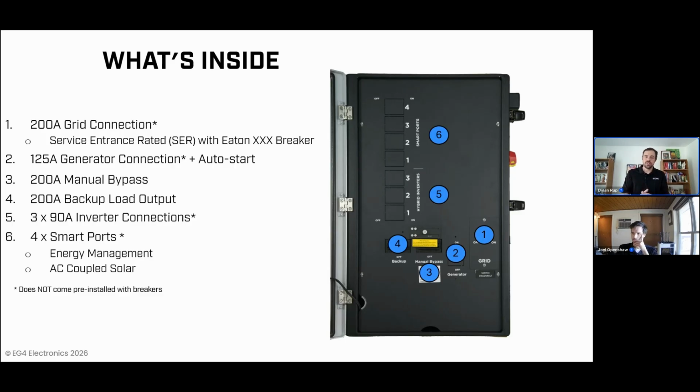And I'll also mention here, like Joel just alluded to, you might already have that first means of disconnect for certain AHJs. We've certainly encountered this. We'll say, hey, NEC code might allow that GridBOSS to act as that service entrance point of interconnection. We, in our local jurisdiction, require a knife blade disconnection. So do always make sure you're leveraging conversations with your AHJ on the design side so you don't get surprised on inspection day that, hey, we actually need to have a knife blade disconnect here for